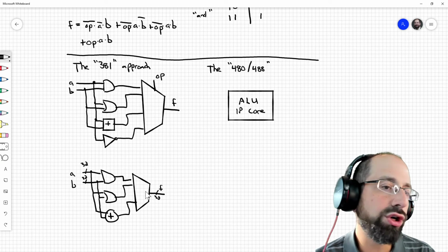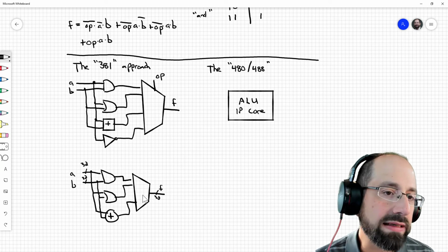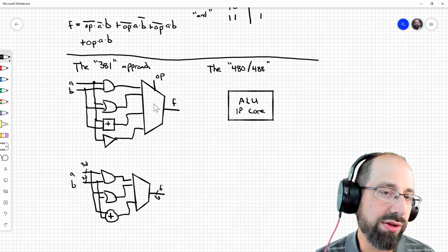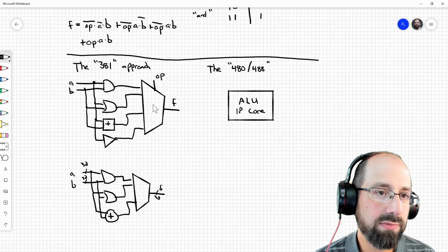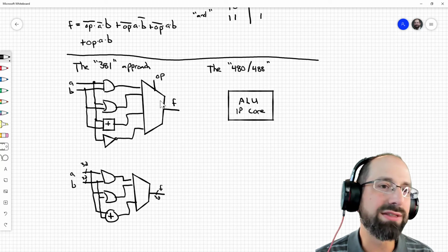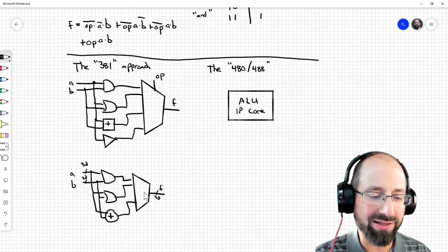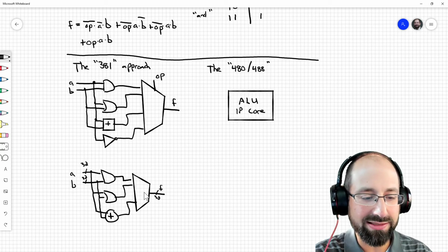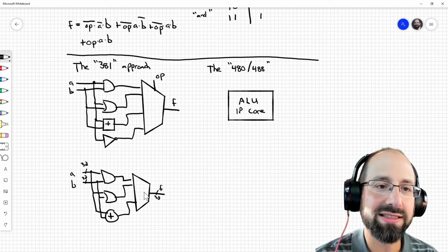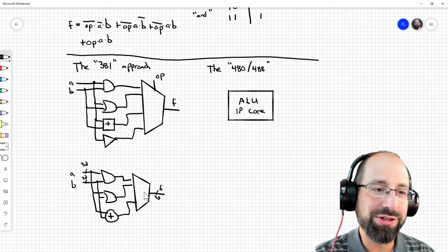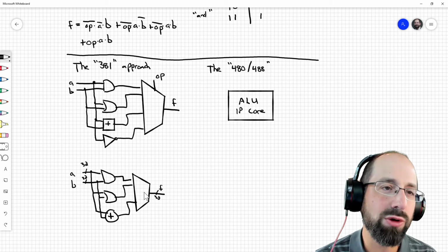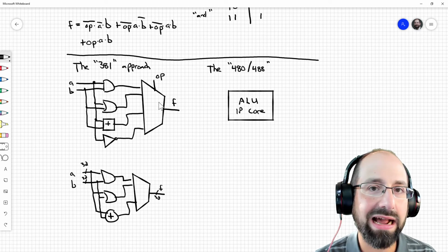Right, and this is a 32-bit N to 1 mux versus a 1-bit N to 1 mux. It doesn't really matter whether it's a single bit mux or an N bit mux. It's the same amount of muxes, right? There is no actual N bit mux. It's just N of those 1-bit muxes kind of near each other, adjacent to each other in my diagram. You wind up getting the same exact circuit back out.